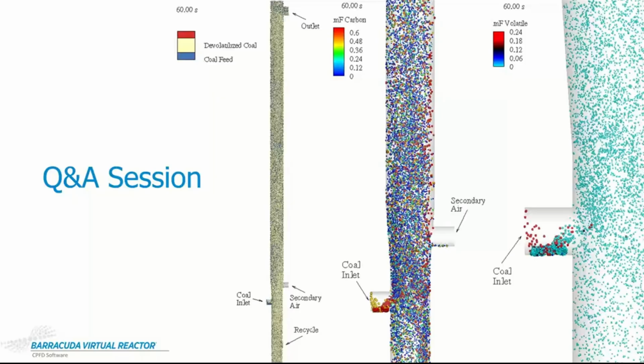So the volatile composition is actually provided inside the paper. They provide us with an ultimate and proximate analysis, essentially. All of that is listed and available, which is what we actually use to define it here. So when you define a particle of the fuel, that is where we're defining how much mass of it is solid carbon versus how much of it is going towards gases. All of that is taken into account from the provided information.